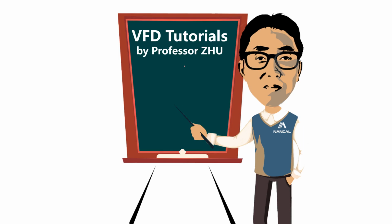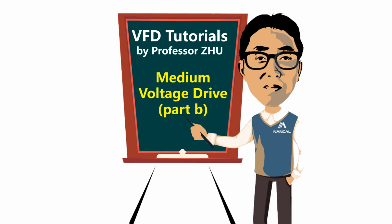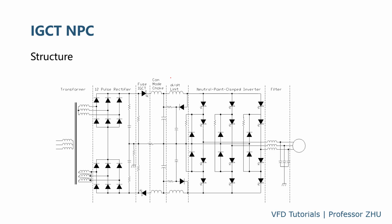Okay, in this section we continue with the medium voltage drive, part B. We started with the voltage source medium voltage drive. The first one is the NPC drive, which uses the IGCT as a power electronic device. NPC stands for neutral point clamped, or sometimes we call it a three-level inverter. And this one uses the IGCT, integrated gate controlled thyristor, as a device.